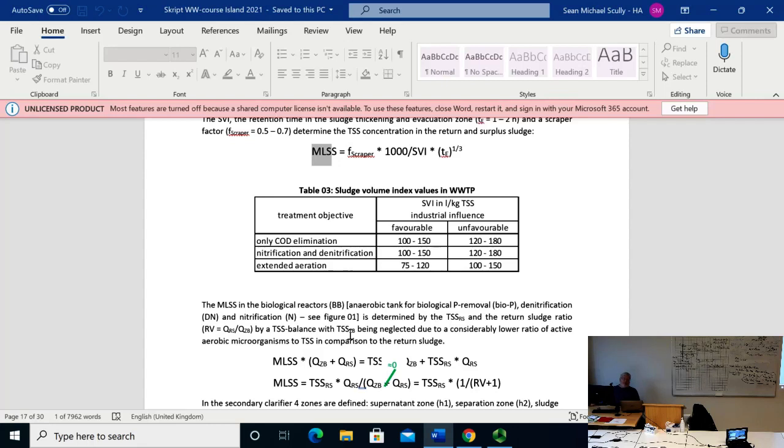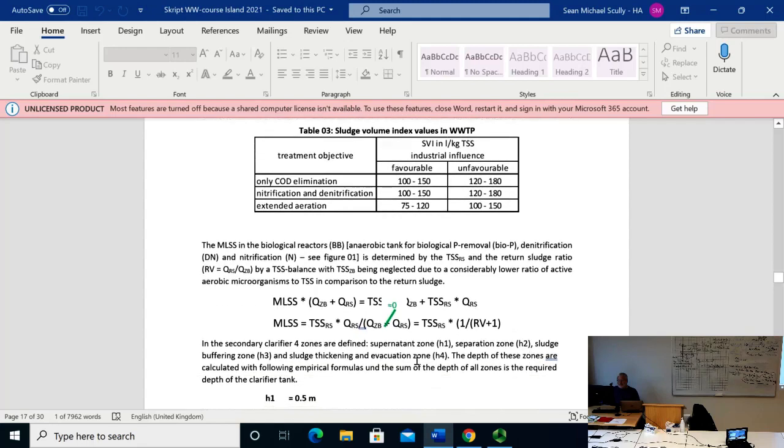So you have to take those off, no? And then you're with 400, then you're below 10% of the inflow. And so we just neglect that. And then we calculate the MLSS, and this is a formula which I've deduced before, no?